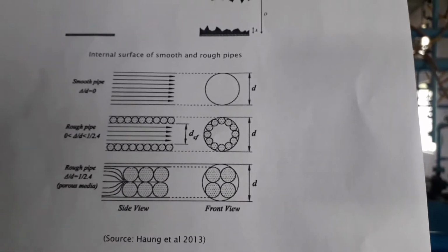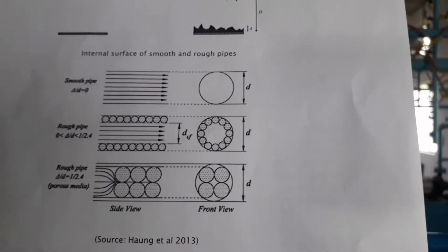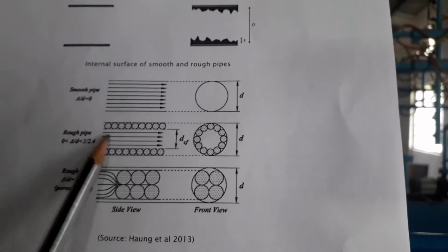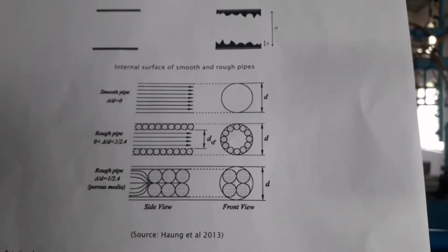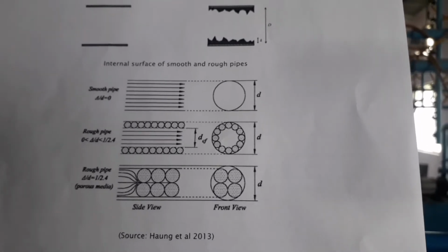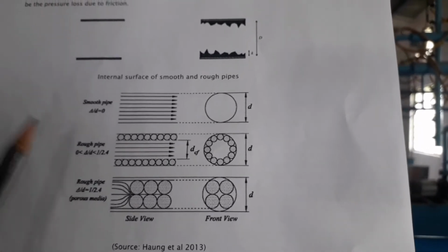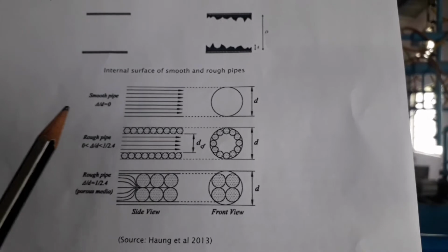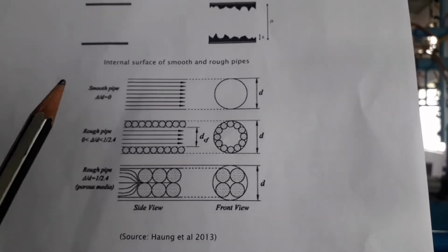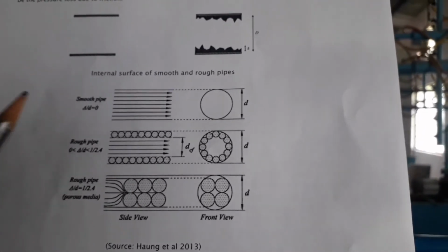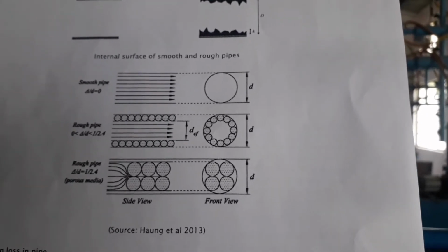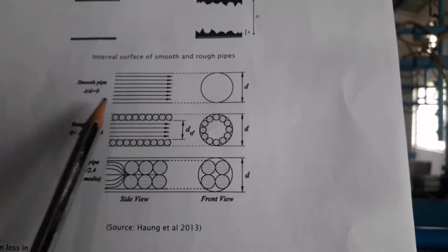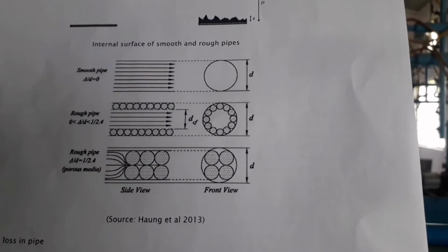Normally the friction loss in a uniform straight section of the pipe is known as major loss, and it is caused by the effect of viscosity, the movement of fluid molecules against each other and against the possibly rough wall of the pipe. It is greatly affected by whether the flow is laminar or turbulent. Laminar means this smooth flow, turbulent means the waving one.